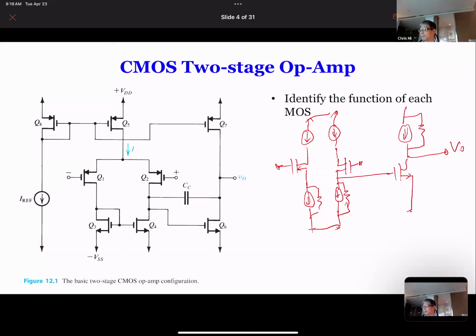So I want to identify a few things here. Now, this one here, of course, is a PMOS, and this is PMOS, and this is NMOS. Over here, the resistance can be neglected because this is at the source. So the first stage is common source. The resistance at the source can basically be neglected because eventually they look like a short circuit. And here you have 1/2 I, and you have RO2, RO3, and RO4.